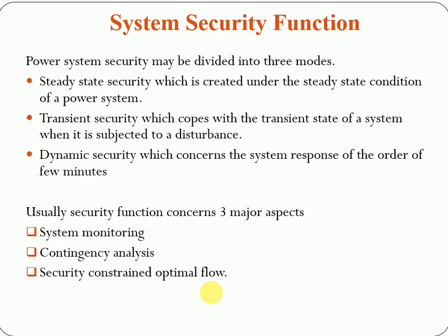By account of the complexity of the task, the data will be processed by digital computer and then arranged in a database, which gives the operator the chance to display the information on large display monitors. The computer can also identify an overload condition or voltage violation by comparing the incoming information with the given limit and remind the operator in time.